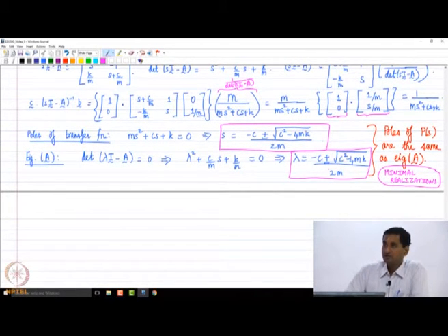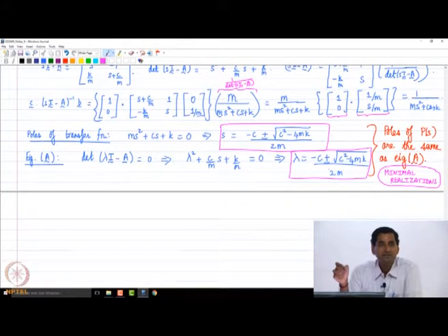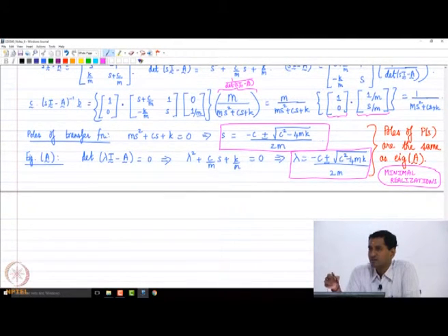Okay, yeah, fine. But why is this important? Because you will immediately see the concept of stability, right? In fact, we will learn what is called stability about an equilibrium state when you go to state space based control. But you can immediately feel that for BIBO stability, we wanted all the poles to be in the left of the complex plane, right? If you used a transfer function approach. So similarly, if I use the state space approach, for asymptotic stability, what should I have? I should have all the eigenvalues of the state matrix in the left of the complex plane because the set is the same, right?